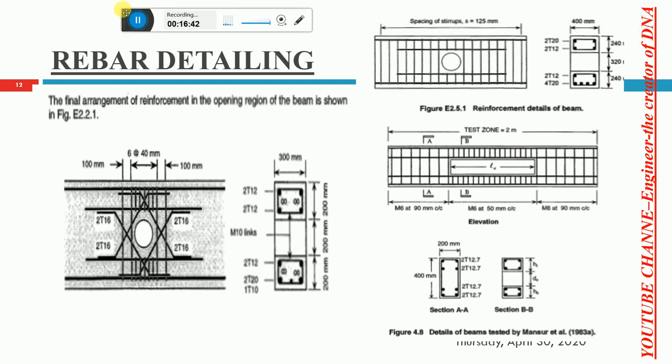Then the reinforcement details for the beam openings follow. These are typical, a different type of reinforcement because of the lesser stresses. You can provide it like this in the horizontal to give some safety to the structure, but eventually providing it like this will be the safest for the structure, in order to avoid all the cracking phenomena. Now we can check beams with openings in rectangular form.